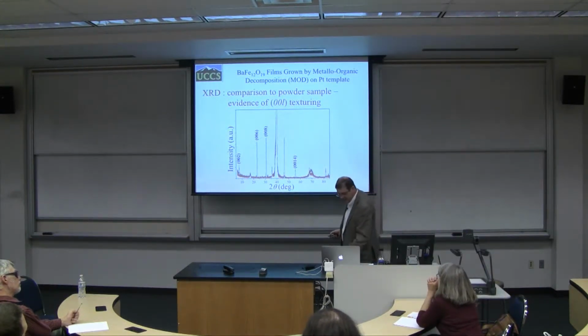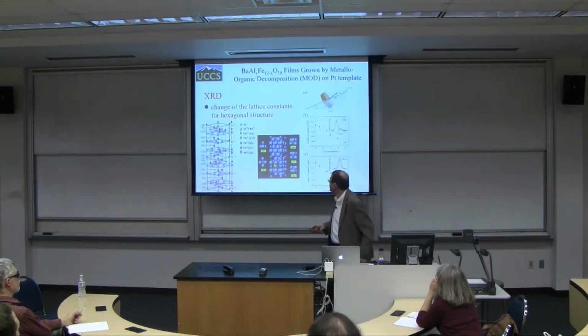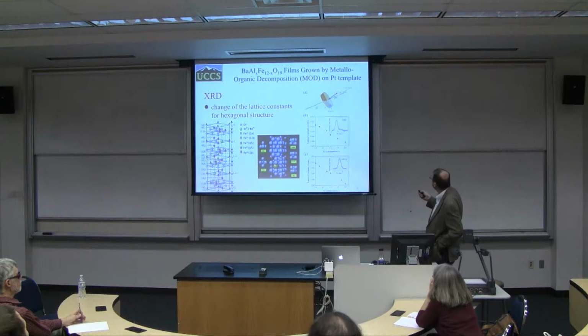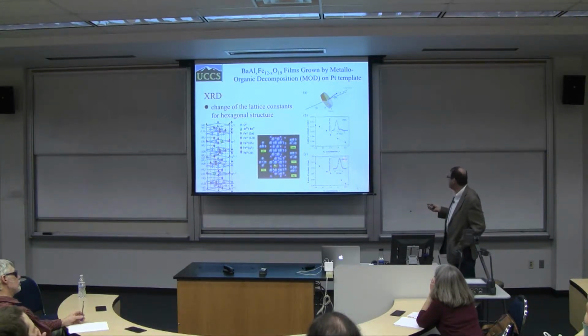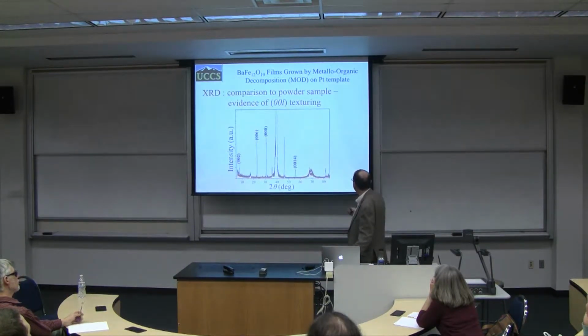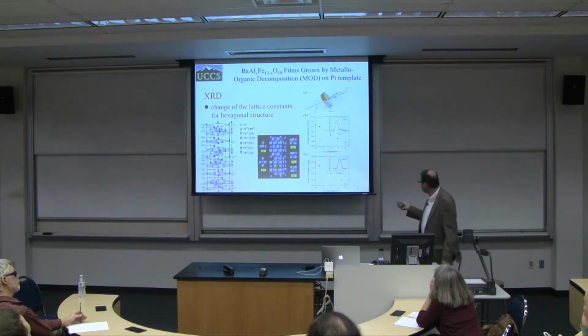My material is hexagonal, and we have done a very careful analysis by measuring at an angle theta between the normal of the sample and also measuring at certain angles. So we were able to pick up, for example, the reflection from 0014. One more time, we measured the position of this peak as a function of composition, and were able to determine the C lattice constant.